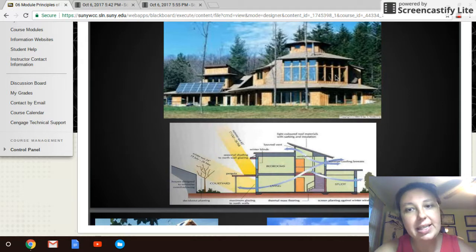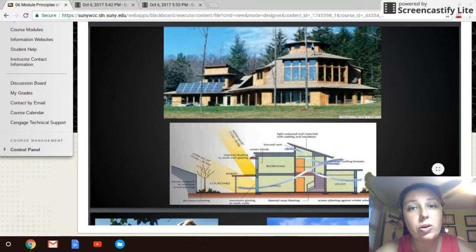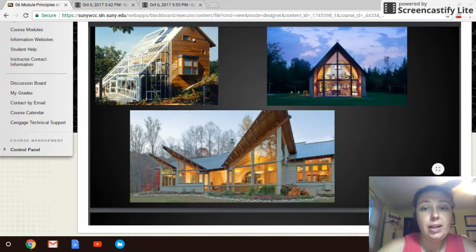And we're maximizing sunlight. So this is an orientation to the south in this case, and I'm taking advantage of the sunlight. And I have good angling of the roof so I can block out the sunlight I do not want in the summer months, but I can maximize it when the sun is low in the sky. It can get right in my winter months. And once again, good control and ventilation systems within it, right? So this is my structures and how I'm getting my air around. Some more examples.